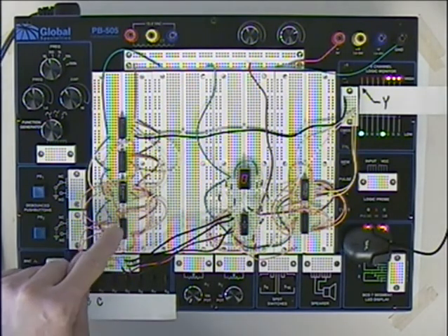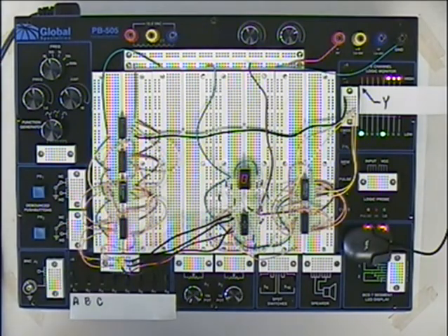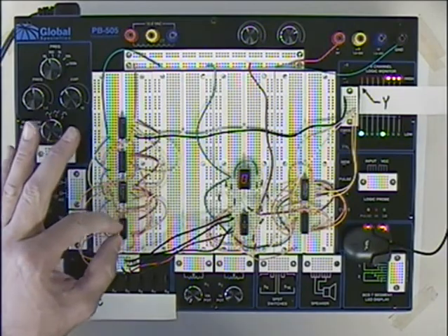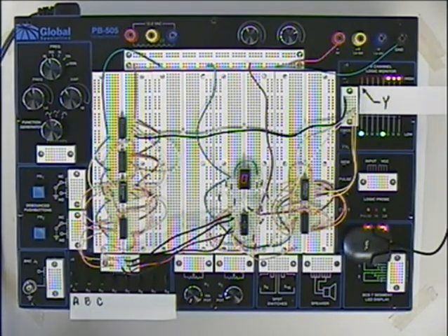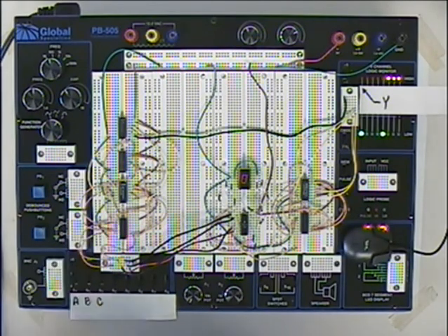Okay, so if I suspected that a chip was bad, I could easily pull that chip out and put a new one in there. You have to be careful to pull the chip straight out so that you don't bend the legs, the pins on them. But if I put the wires over the top, it's probably more convenient. But if I then have to pull the chip out, if the chip's been burnt up or abused or something, then I have a problem getting it out of there.